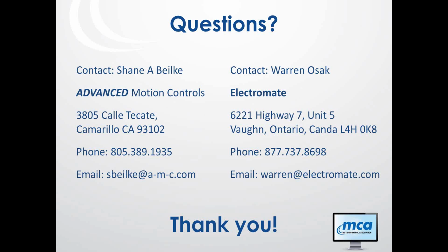How do you control motors with low inductance? Motor manufacturers are trying to make their motors as efficient as possible, and they use models to develop these motors. A lot of those models lead them down a path to very low inductance to achieve the efficiency goals of the motor design. When you couple that with a servo drive, the servo drive needs inductance in the motor to operate because it's a switching device. You can add an inductor between the drive and the motor, but you're really defeating what you just tried to achieve in your motor design. We're effectively just adding inductance back into the system and wasting energy running current through those inductors.